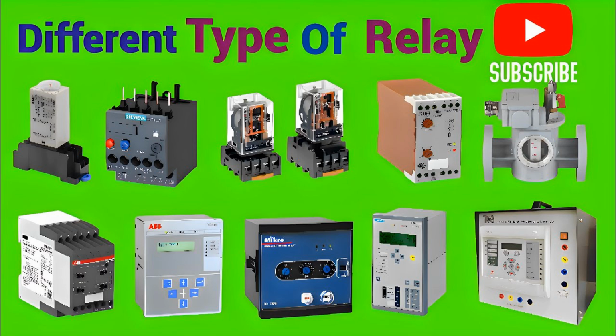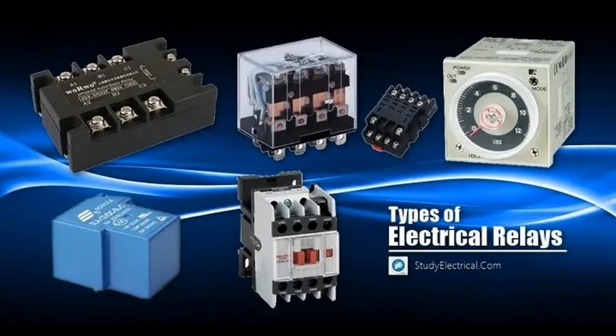Contact materials and design. The materials used for the contacts and their design play a crucial role in determining the relay's performance characteristics, such as contact resistance, contact bounce, and contact life. Contact materials must be selected based on factors such as electrical conductivity, resistance to arcing and welding, and resistance to mechanical wear. Contact arrangement. Relays may have different contact arrangements, such as normally open, NO, normally closed, NC, or changeover,